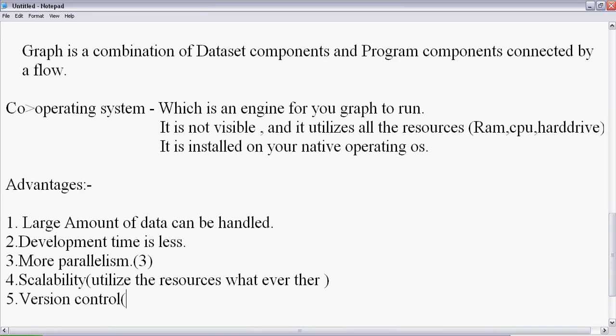The file f1 is saved as f1, and whenever you take and update that file again, it will create f1.1. Again if you update it, it will create f1.2. In this way the versions will be maintained. Where will it be maintained? Under EME. Under EME the version control is maintained.